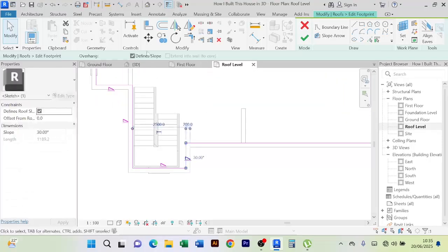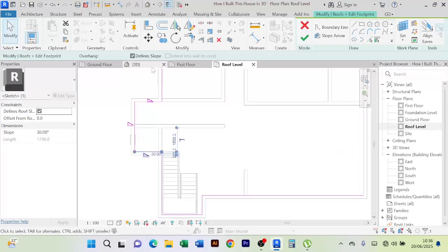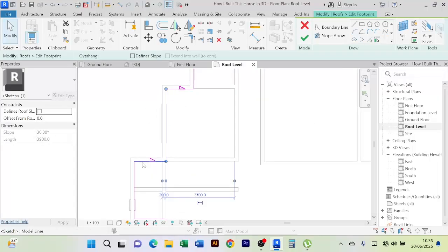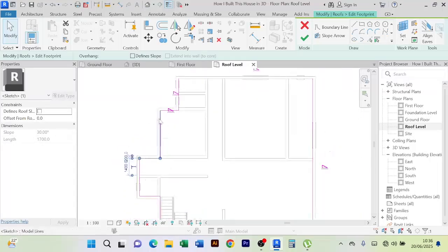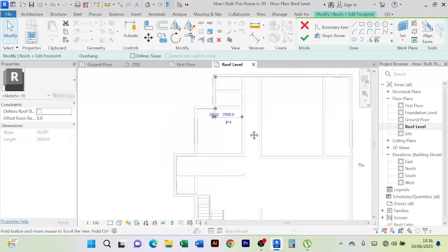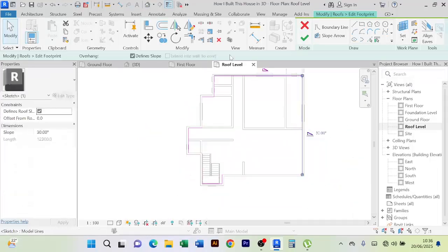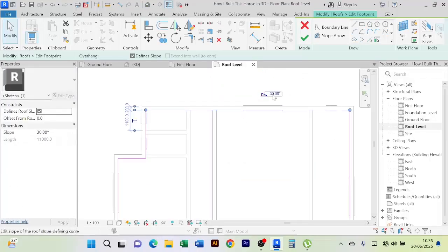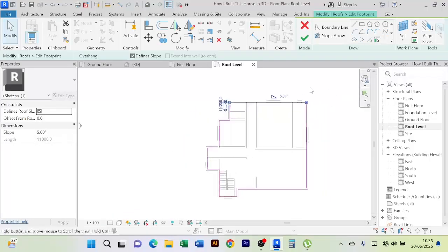We shall do it for all these other ones. You keep unchecking the slope like this. You uncheck almost all of them, just like that. You have to keep unchecking, and then this side you uncheck. For now, let us leave only this, and when you click on it, we are going to change the degree to just 5, just to slope by 5 degrees.